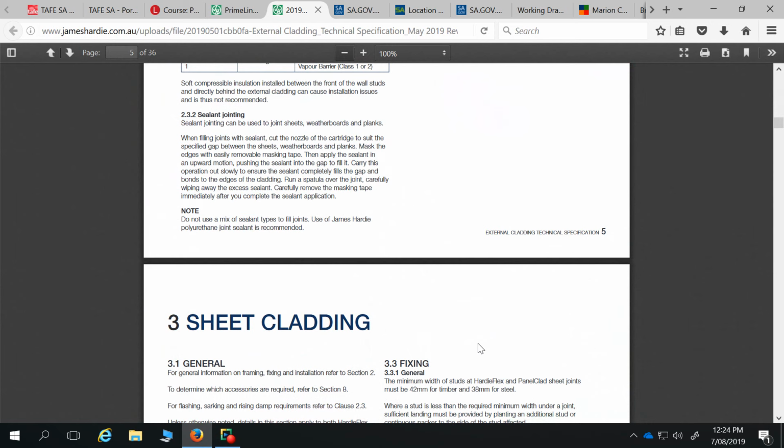Then on that outside layer, you want to apply a pattern to the foreground, and the pattern will be horizontal model lines. Next week, when you've got into all your research, I'll go through and start showing you the difference in that. But when you set up hatching patterns in a 3D environment, because we're going to orbit this model from the outside, and some views might be perspectives and that sort of thing.